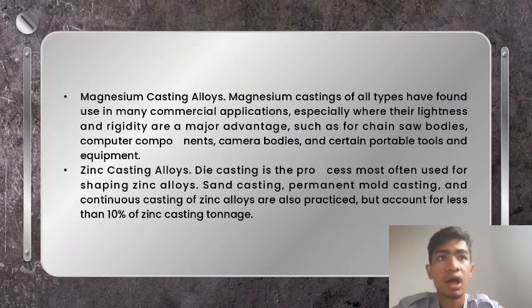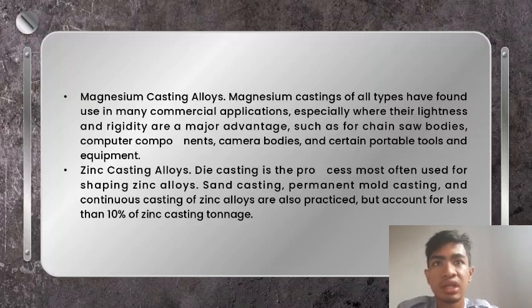Aluminum casting alloys. Aluminum casting alloys are the most versatile of the common foundry alloys and generally have the highest castability ratings. As casting materials, aluminum alloys have these favorable characteristics: 1. Good fluidity for filling thin sections. 2. Low liquidus temperature relative to those required for many other metals. 3. Rapid heat transfer from the molten aluminum to the mold, providing shorter casting cycles.